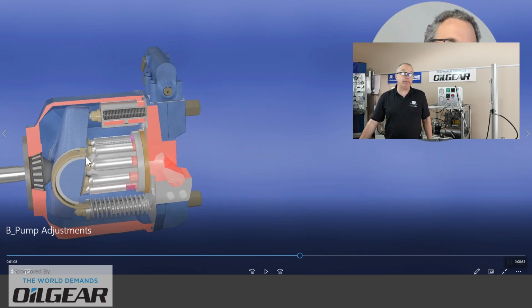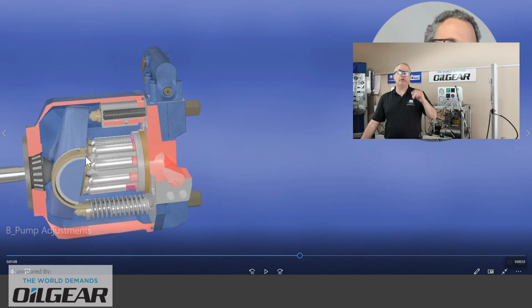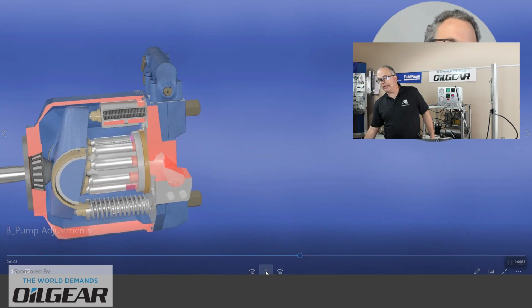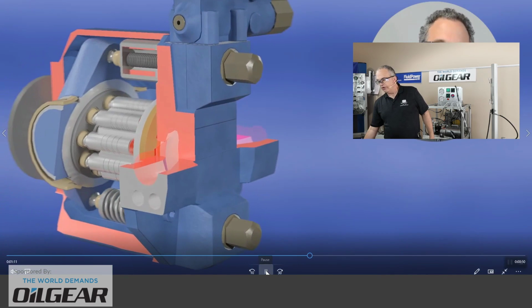It's not a very steep angle. The large majority of pressure compensated piston pumps don't tip that swash plate too far past 20 degrees. There's the odd one at up to 22 degrees. Some very heavy duty pumps, this angle is only as much as 15 degrees. So it doesn't look like all that much when you see it from the side.